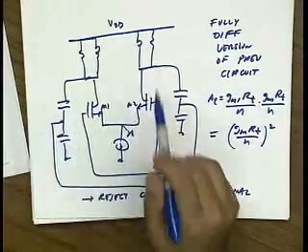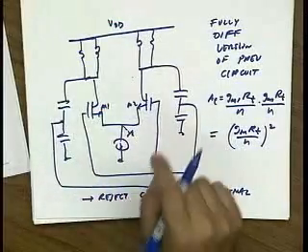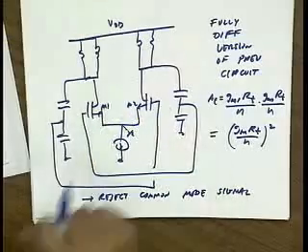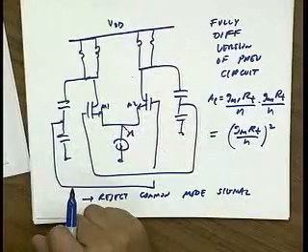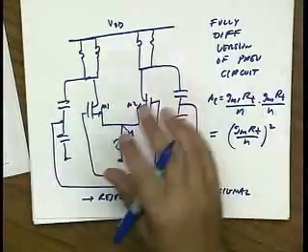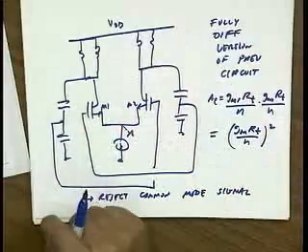So this is a positive feedback amplifier with loss of gain. That's a simplified way of looking at it. Any noise signals near the center frequency of the tank will influence the tank in a substantial way, and that's a really bad thing. We don't want any disturbances near the center frequency to influence this oscillator.